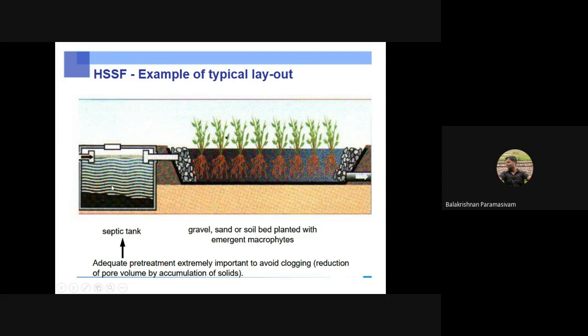But in the case of a septic tank, it works by the anaerobic process, and the constructed wetland works on physical, biological treatment processes, and also phytoremediation. So mainly to avoid clogging of the filter media, if you provide a septic tank kind of structure, we get high quality effluent and it won't affect the process.